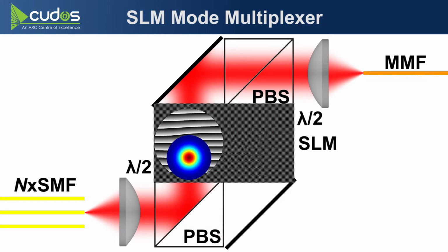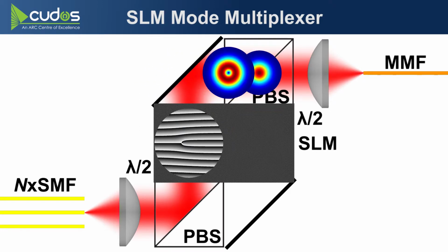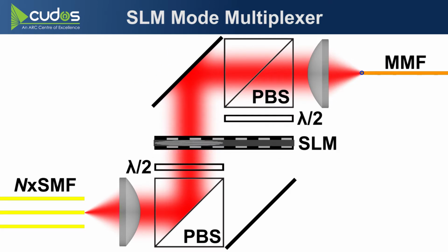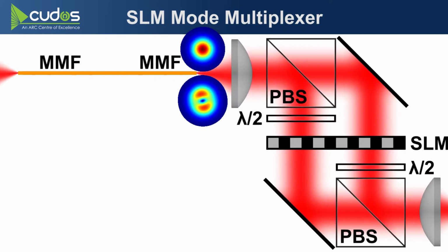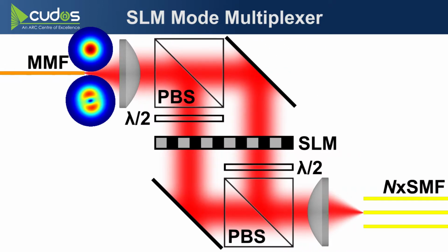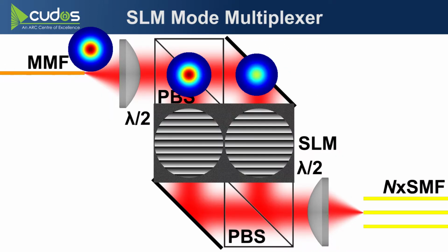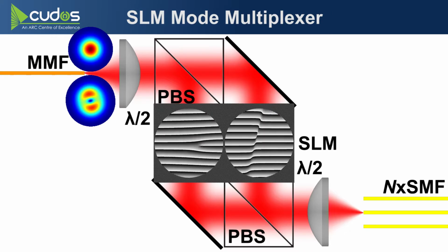So the system launches both the mode of interest and the reference mode simultaneously in superposition, couples them into the fiber. They arrive at the other end after some mixing. Now each of those modes have their own detection phase mask pattern. So you interfere those two masks together to work out their relative phases. And now the entire matrix is defined in a meaningful way.